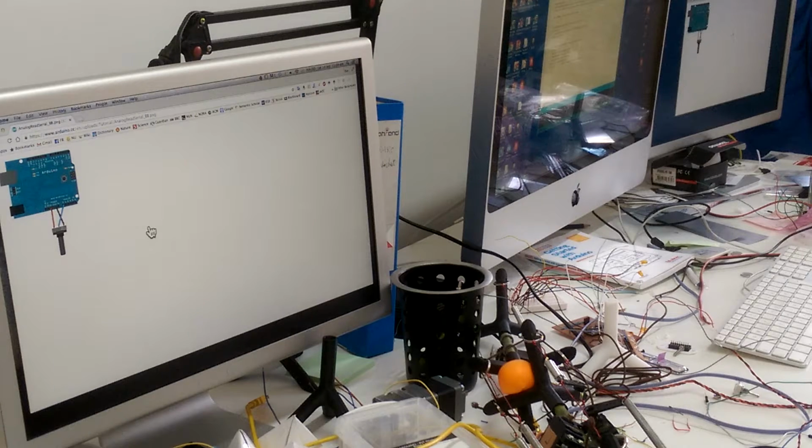The basics of a breadboard is that when you take the breadboard, all these pins are connected together. Then there is a disconnection, and then all these are also connected together in these, if you want, vertical lines. So these 5 are connected together, but they're not connected to the next one.